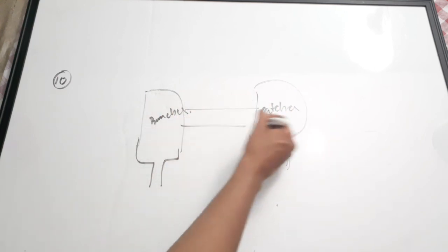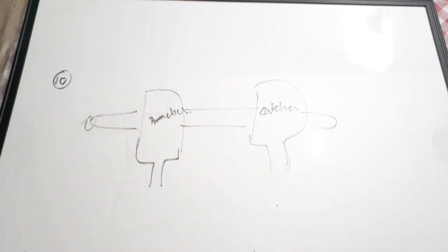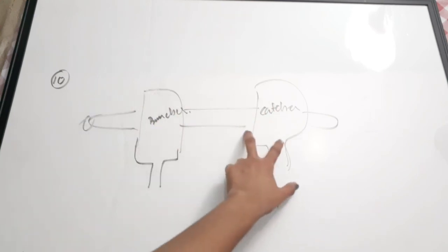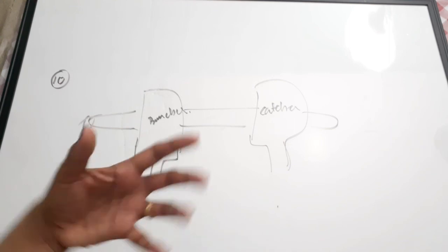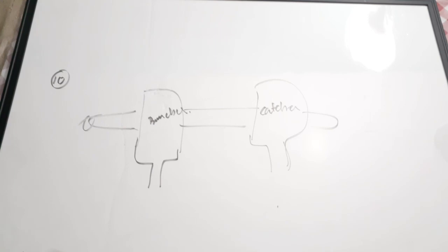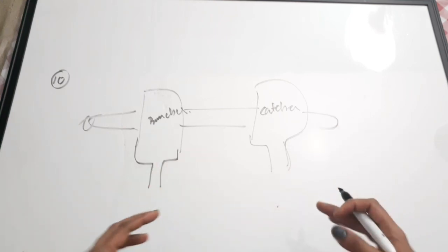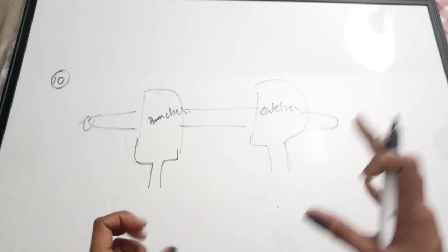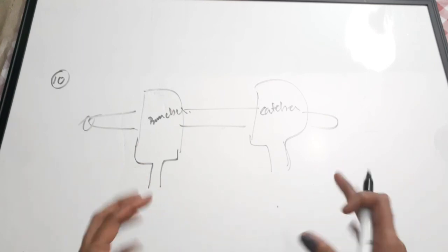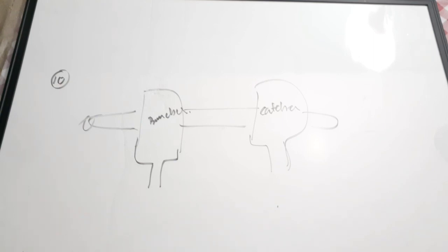So the electrons pass through these two cavities and get velocity modulated and become higher velocity electrons. Electrons pass through the buncher and the catcher cavity, and they get accelerated, and finally after passing the catcher cavity, this high velocity or kinetic energy is absorbed by the microwave which we want to amplify, and the electrons get slowed down. Okay, so that is the brief working of a klystron, and the process happening here is called velocity modulation.